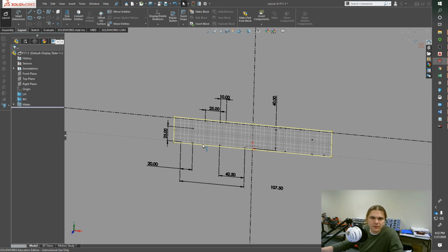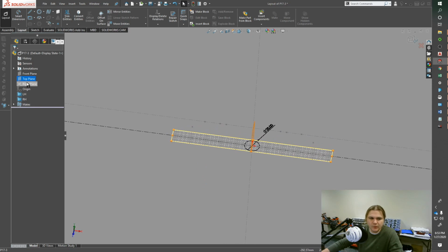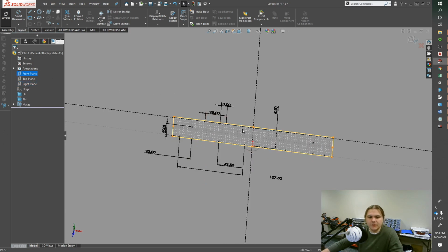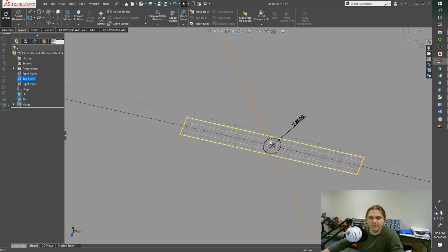How a 3D sketch works is just like any sketch, but the only difference is now you actually can swap between your different planes on the fly. So if I wanted to start doing a sketch on the top plane, I just simply double click on it and now I'm sketching on the top plane. Right plane, front plane. As you can see here, I got some construction lines, several points, and then on the top I have this whole circle. The circle is what I'm having control the entire assembly. As I change my drill diameter, that will reposition my parts as needed.